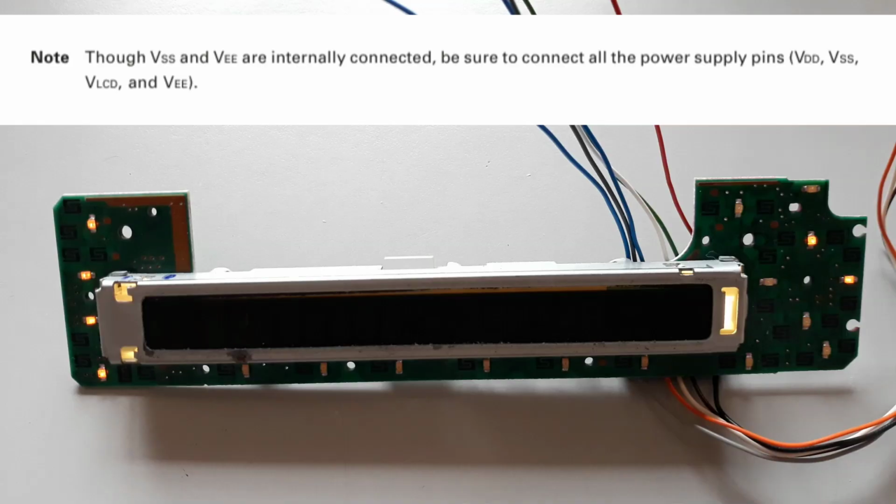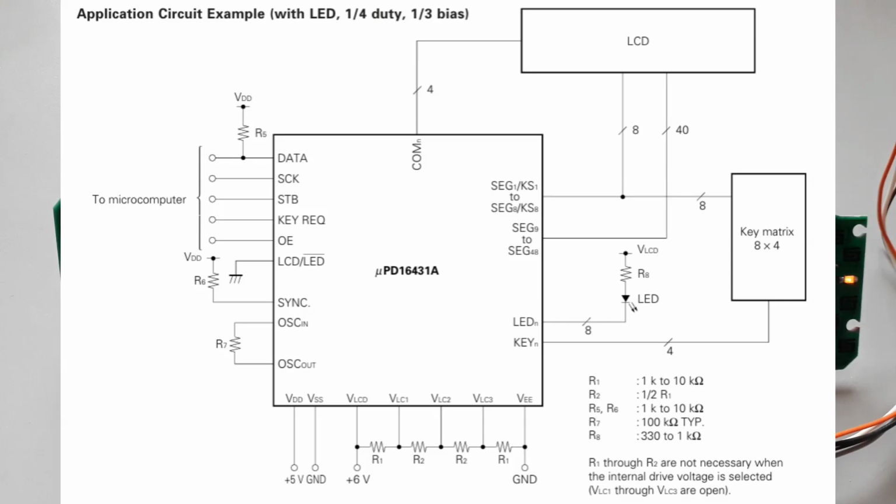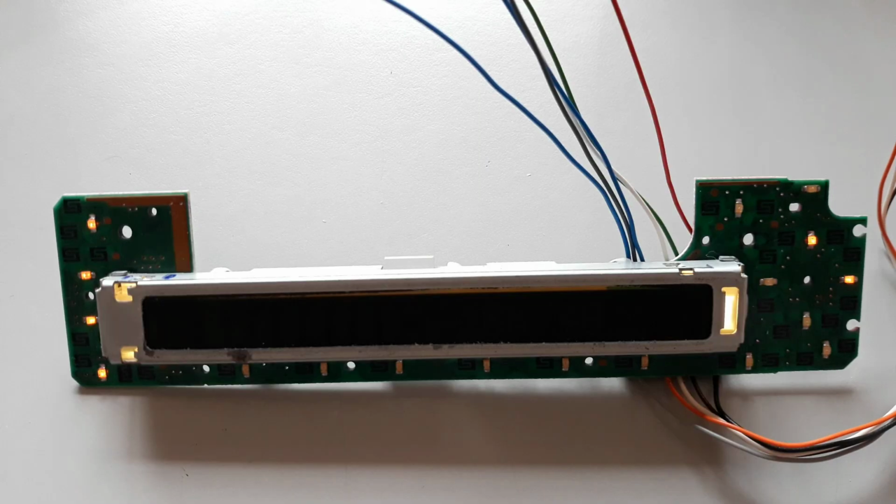The driver allows either an external resistor divider or its internal voltage divider to generate these bias levels. One interesting point is that the datasheet recommends a VLCD supply voltage of 6 volts. However, on the panel we are using, VLCD is connected directly to 5 volts DC.